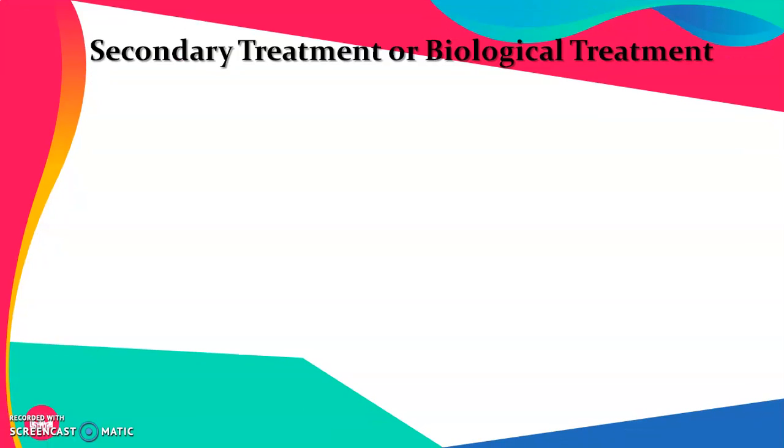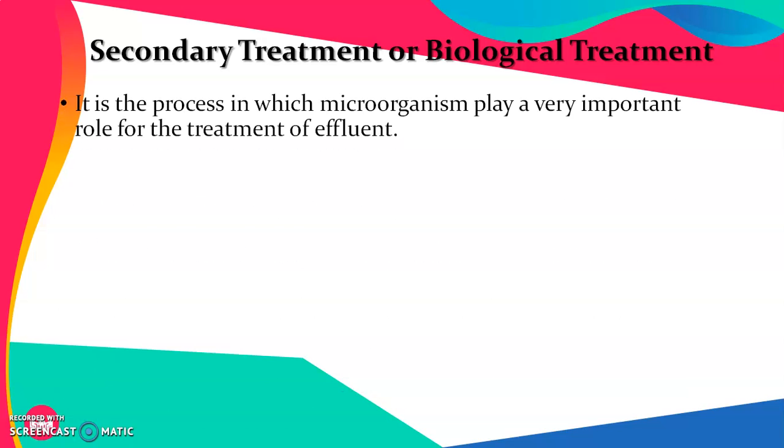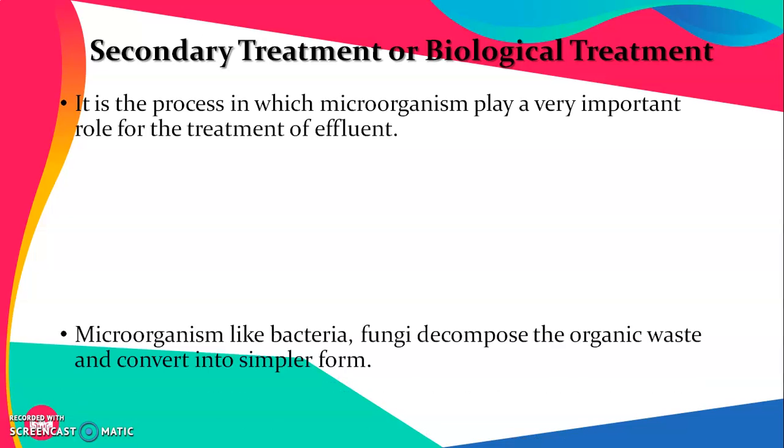After that, the secondary treatment is used. Secondary treatment is also called biological treatment. The major reason behind this is that we take the aid of bacteria or biological forces to treat the water. It is a process in which microorganisms play a very important role in the treatment of effluent.